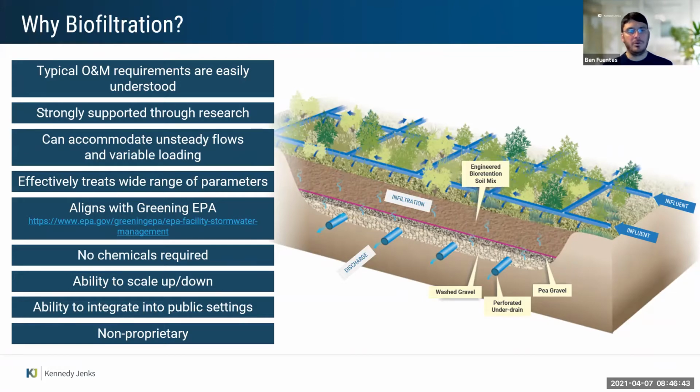And then a couple more, because of the aesthetic, it's a green approach. You can have some flexibility in the plant selections, and you can shape it in really any configuration you want. So it provides a lot of flexibility to integrate into public settings. And then the last one there is that it's not proprietary. There are proprietary forms of biofiltration, plenty of them, but you can definitely refer to a guidance document or a guidebook and get this done on your own and not be tied to a vendor if that's not preferred over time.